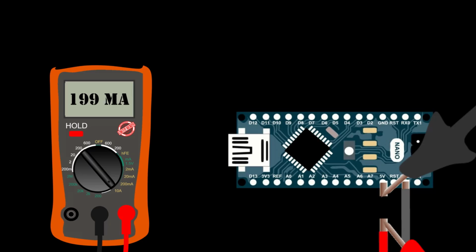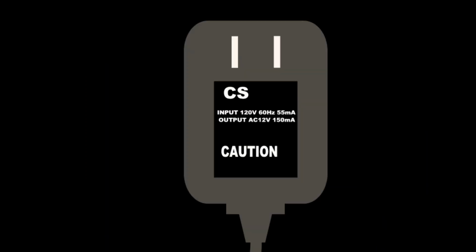It is best to have a meter that can withstand the maximum current of the power source if you connect it to measure current. Power sources have a value in amps that they provide. This value should be printed clearly on a surface that a technician can easily read. For example, a power supply that plugs into the wall may provide 100 milliamps or above 2 amps. This value and the output voltage as well as the input voltage should all be marked on the power supply.